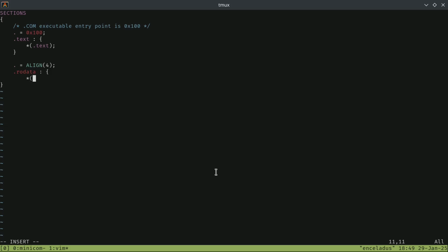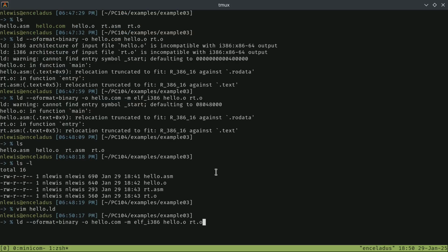While we're currently operating in 16-bit mode, our board does have a 386, which is a 32-bit processor. And the reason I say largest register size is that the Pentium MMX added 64-bit registers for the MMX functionality, and the Pentium 3 added 128-bit registers with SSE. While both of these were 32-bit CPUs, they required up to 16-byte stack alignment to store MMX or SSE registers on the stack. Now if we pass the linker script when linking, we actually output an executable.